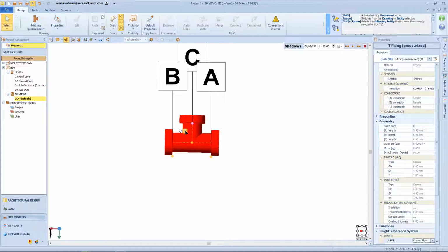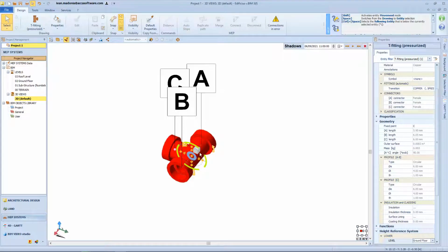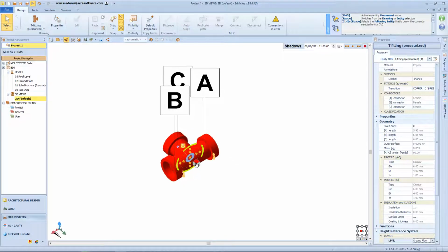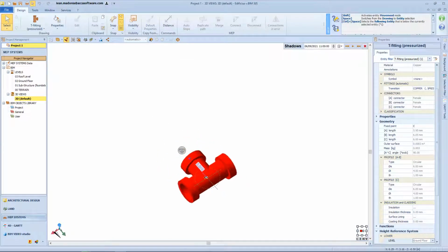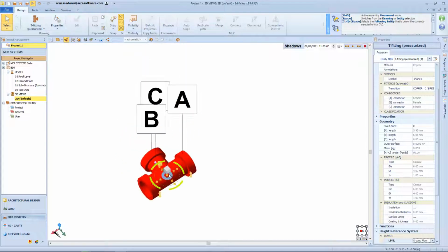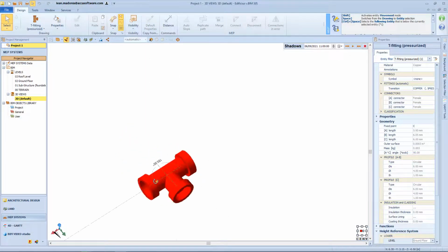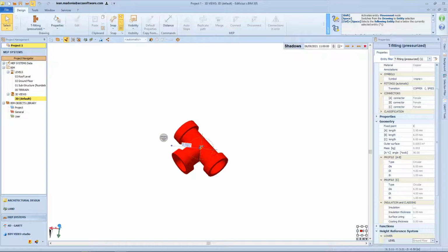The 3 axes next to the anchor enable the object grip. Selecting one of the faces of the cube that appears in association with the object grip, you can also do the following. Rigid displacements of the object according to the direction and verse specified by the arrows. Rotate around the axis by selecting one of the orange circles. Orient the object grip on the top using the green arches.